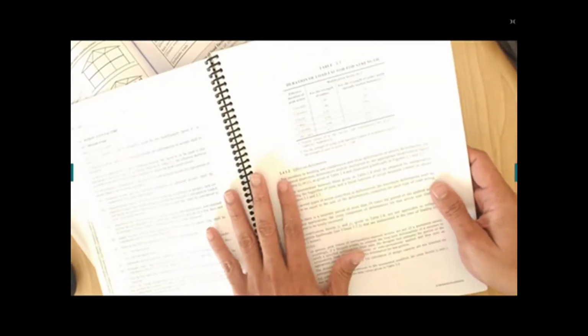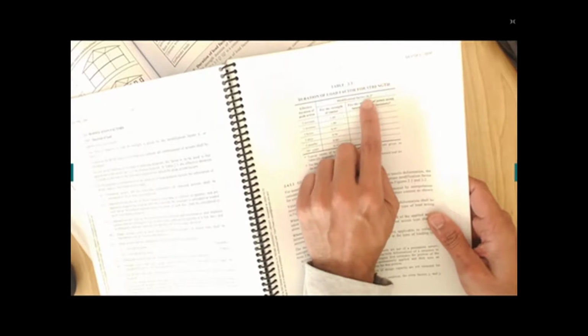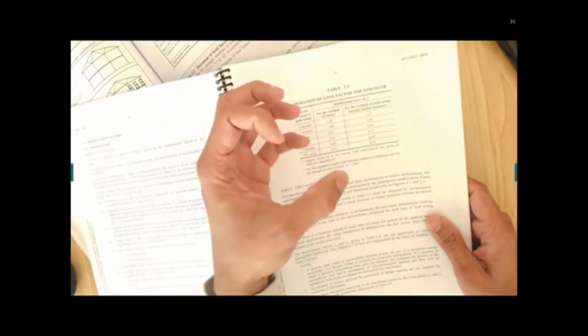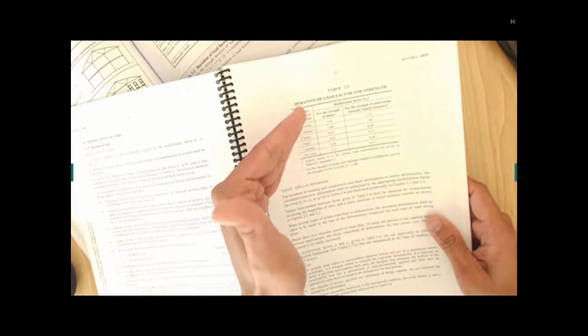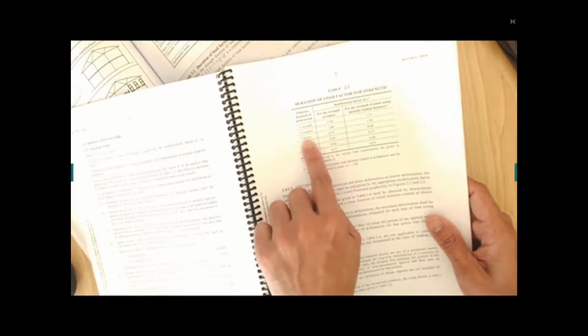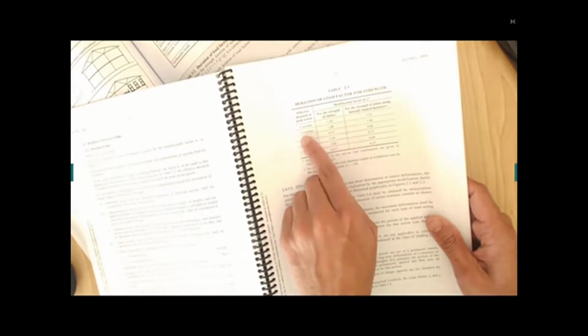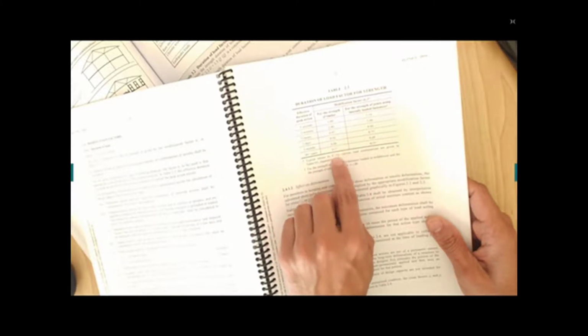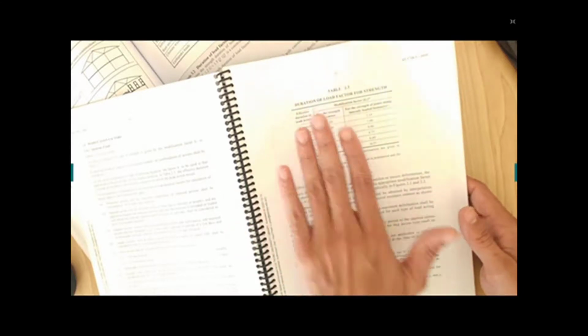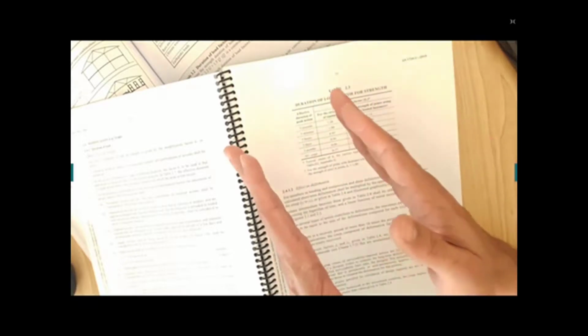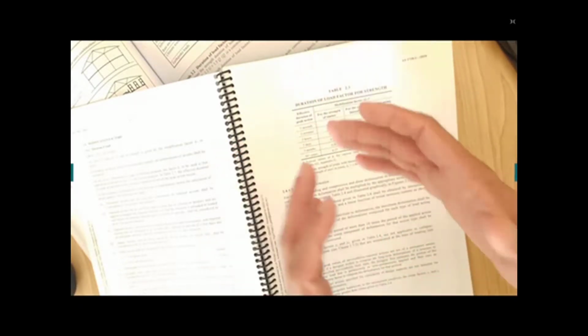So here you have two options. You can use table 2.3 and you have this K1 value given to you. But the problem is you have 5 seconds, 5 minutes, 5 hours, 5 days, 5 months, and 50 plus years. Now these values depend on how sensitive your structure is. Sensitive means how much load is going to come onto the structure. Now these tables do not help, because if you have 5 seconds, you need not reduce it. If you have 5 minutes, no need to reduce it. But for 5 hours and more, your capacity is reduced, and sometimes you will get a significant penalty of about 33%. You can't go for a 33% penalty, right? It's quite severe. In case you want to design something for the whole 50 years, your structure will be getting that ultimate load. Now it still does not help me.